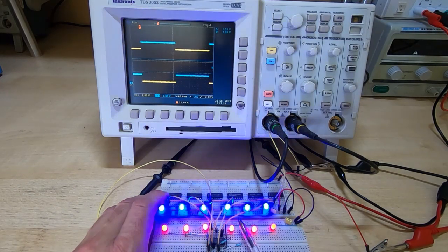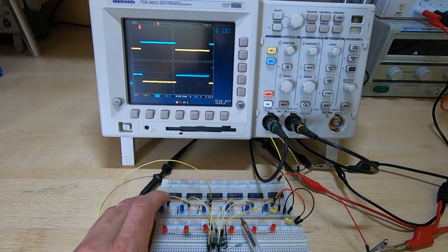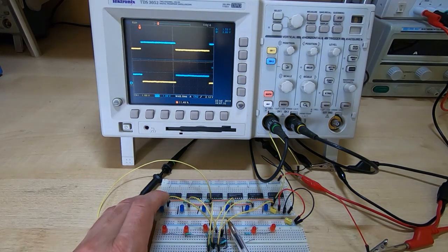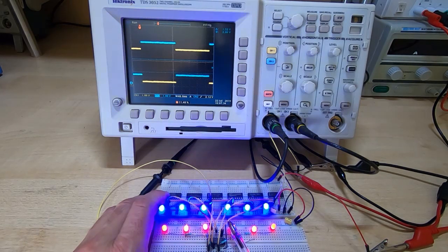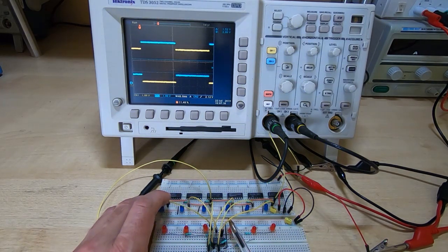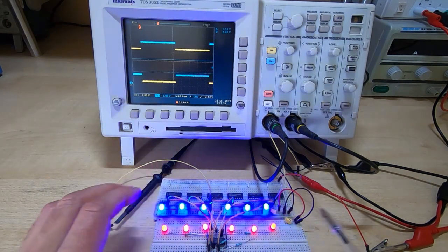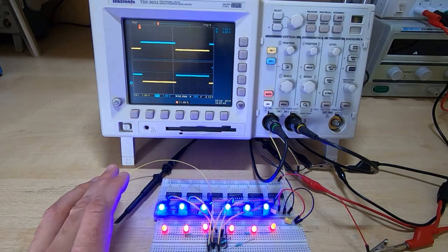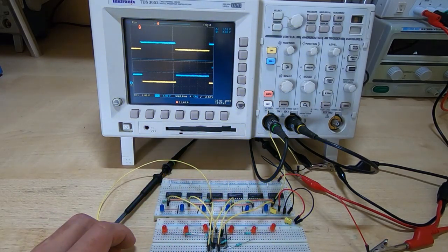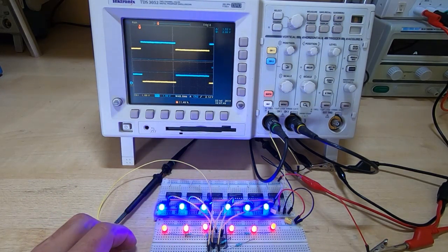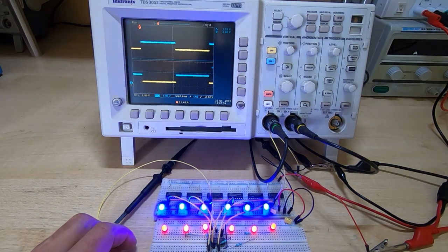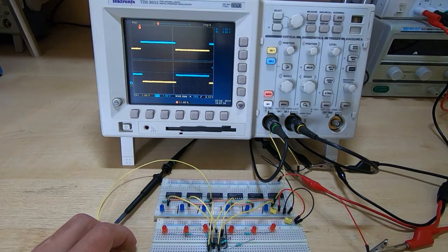The HCU, I was surprised to see that in there, definitely do not use those. The HCT, in theory you can use them, but again I'd advise not to unless you have a very specific need to. But this is an experiment well worth doing if you're encountering noise on the Altair, or what seems to be noise. Just hook a load of different TTL type devices together and you'll see some very strange behaviour as you vary the conditions under which they're operating.